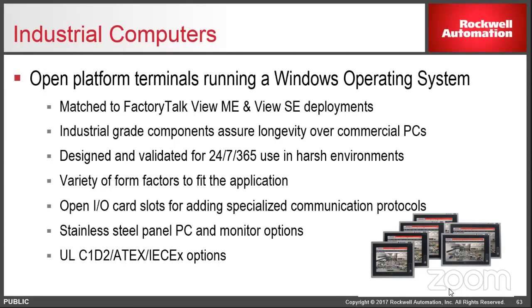So we use industrially rated components like solid state drives and RAM. All the vendors that make those things usually make an iTemp version, and that's what we use in these products. That drives up the cost a little bit, but we built in design thermal margin and EMC and shock and vibe and all that stuff, especially when we're trying to stay fanless. Nobody likes fans. We only use fans when we absolutely have to. Passive cooling is key.